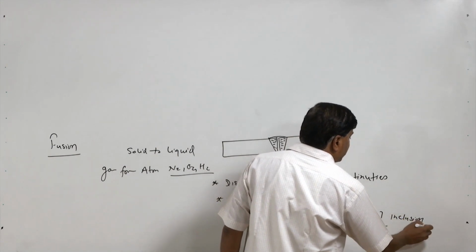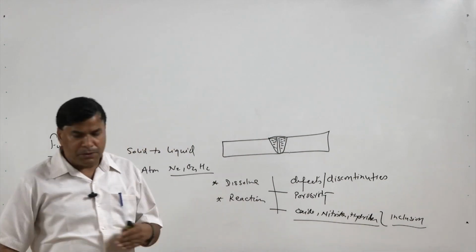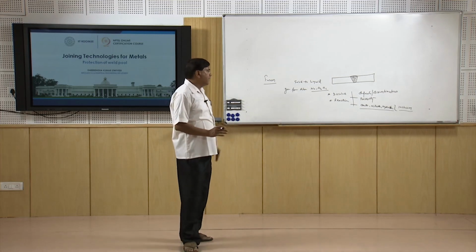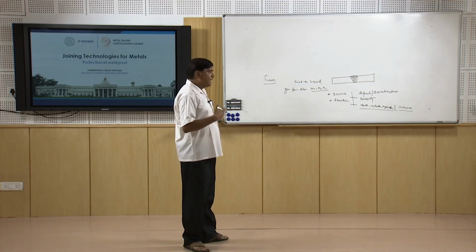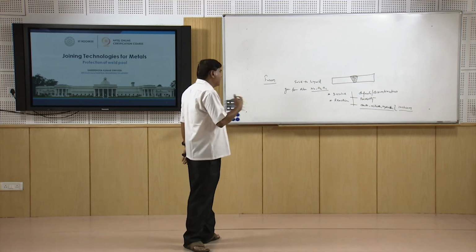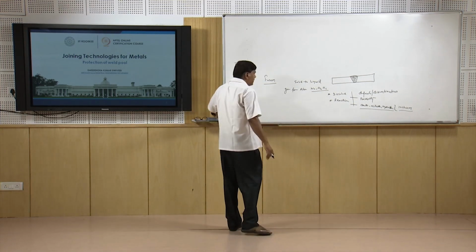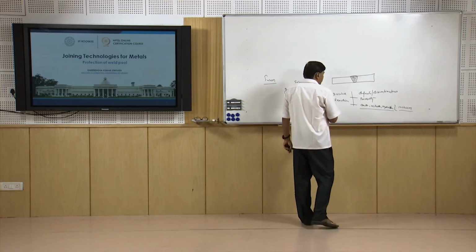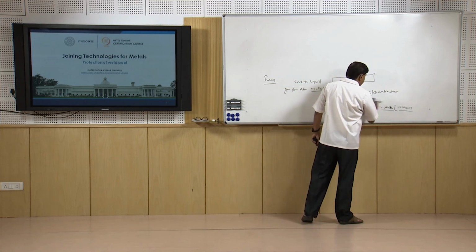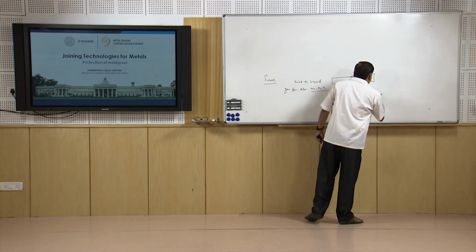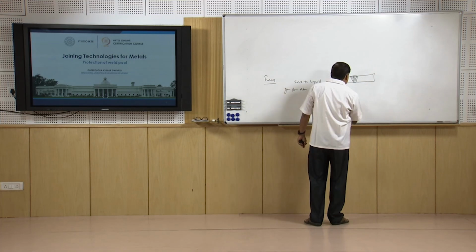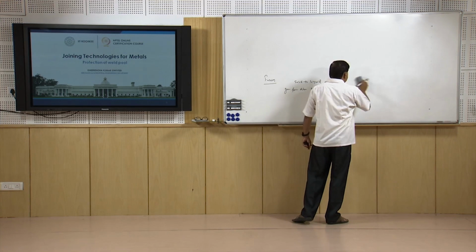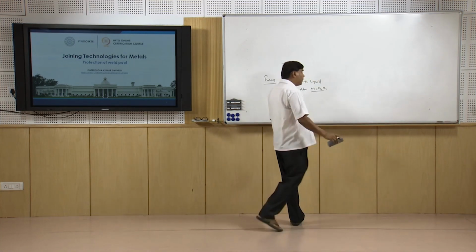So, in both cases, the presence of porosities or inclusions in the weld will deteriorate the mechanical performance as well as other performance expected during service, like corrosion or the ability to carry fatigue loads or tensile loads. Therefore, it is required that during fusion welding, the weld metal is protected using suitable approaches from the atmospheric gases.